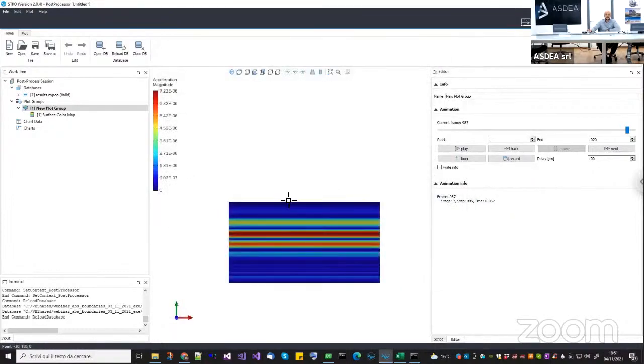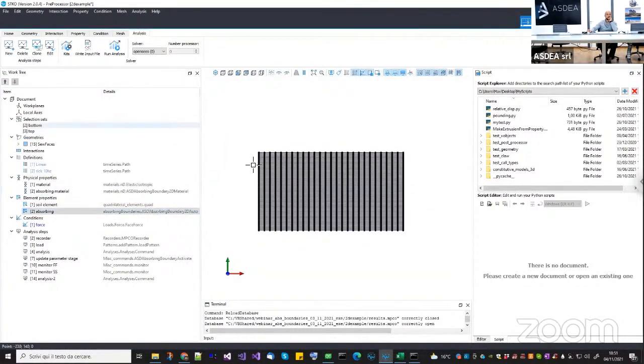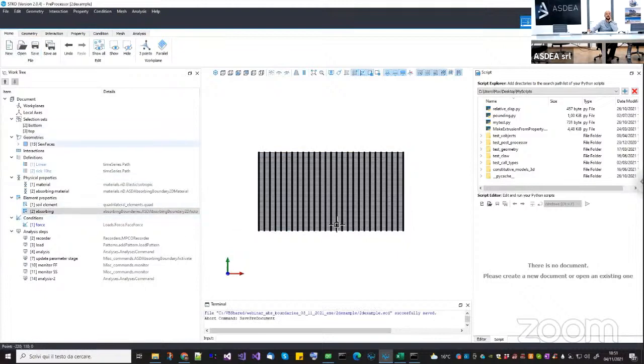For the 3D case, it's the same thing, okay. I will show you how to do it now in the soil interaction model, but you may imagine that the procedure is the same. So you need the update parameter, which is the same. The material is the same, but 3D, and the element is just one and should be applied to the boundary faces, okay. And then STKO takes care of doing the extrusion. Well, this one is fine. Save. So now you know how to convert all of them.